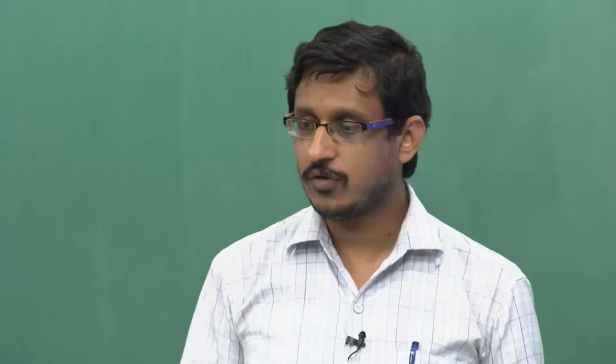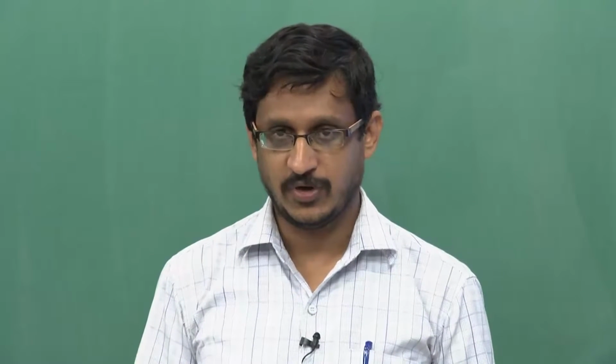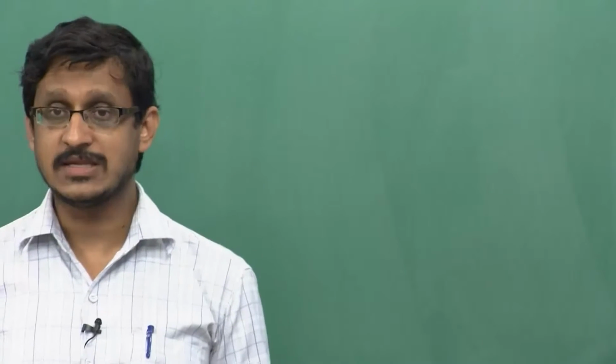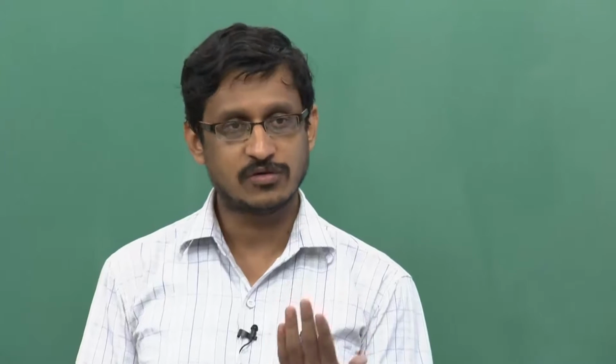Okay. So, before we begin, let us actually look at what makes a good detector. I mean, if I have to use a detector for a 10 Gbps communication system versus 100 Gbps communication system, there has to be certain characteristics of these photodetectors that are important to me, right. So, one would obviously be, if I have to increase the bit rate, I know from my system design part 1 that there is something called as a rise time associated with the photodetector, right. It is essentially the response of the photodiode to a step optical input.